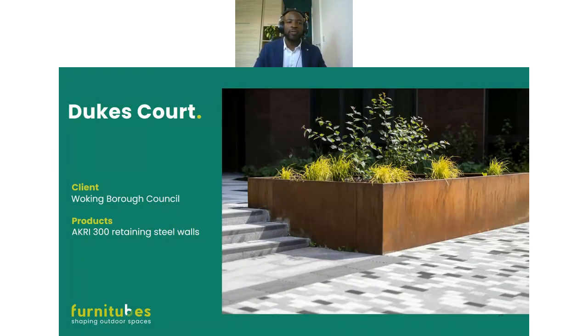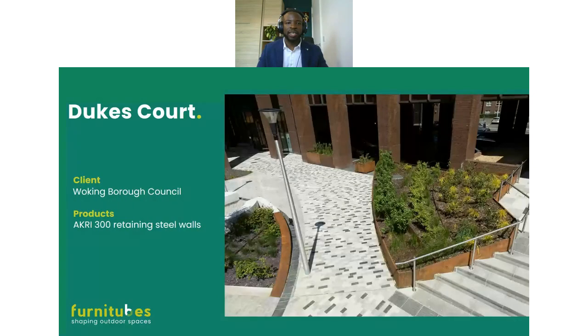And also for the hard landscape, they actually created a gap just to allow for the leaching of the Corten steel when it's still being cured to go straight into drainage rather than onto the hard landscape. This is Duke's Court from another angle.